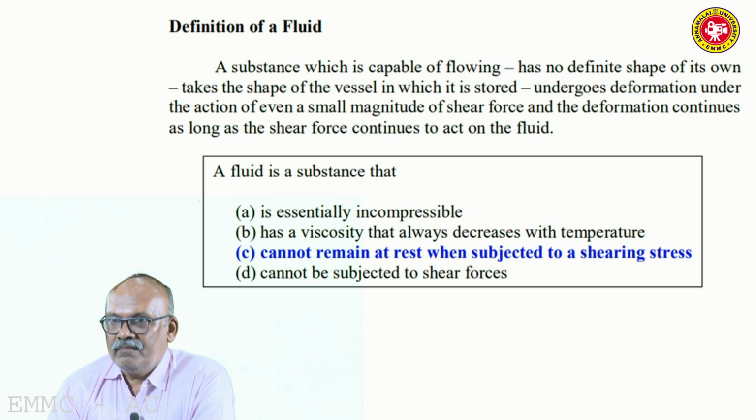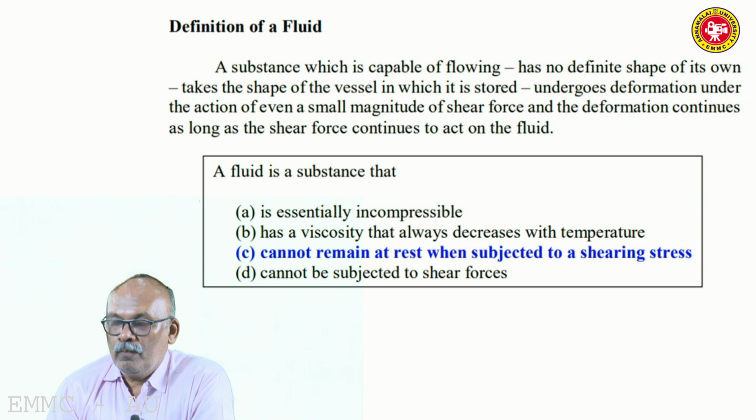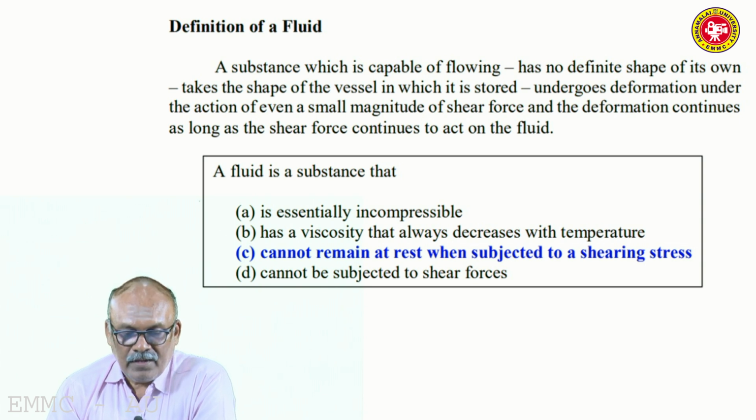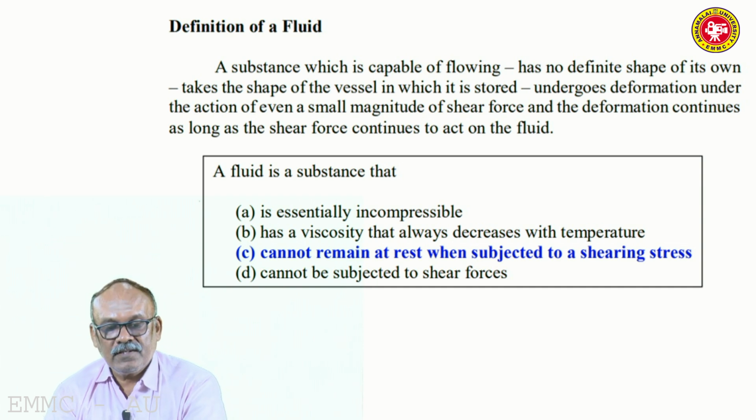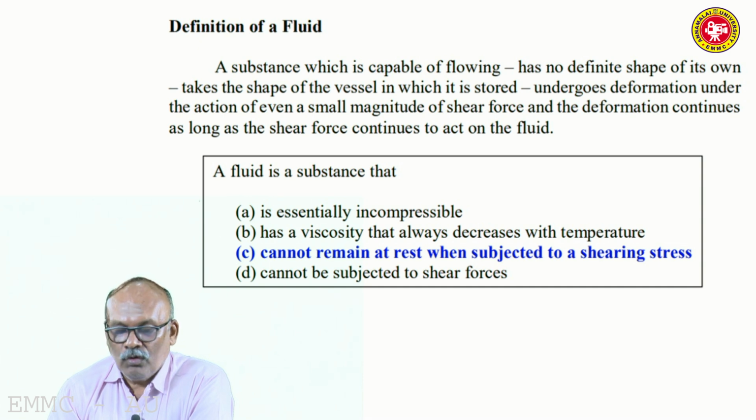Now let us define a fluid. So a fluid is a substance which is capable of flowing. As we already discussed, a fluid cannot resist any shear stress. When it is subjected to a shear stress or a shear force, it will start undergoing continuous deformation as long as the shear stress continues to act, and therefore it changes shape or it flows.